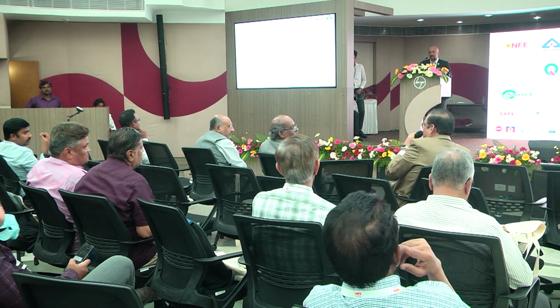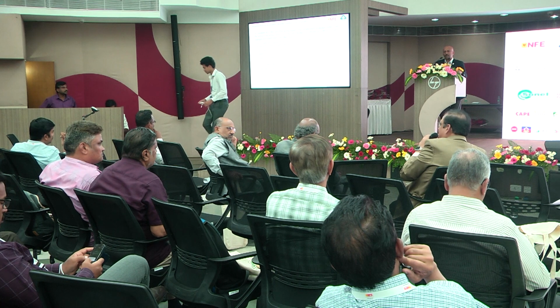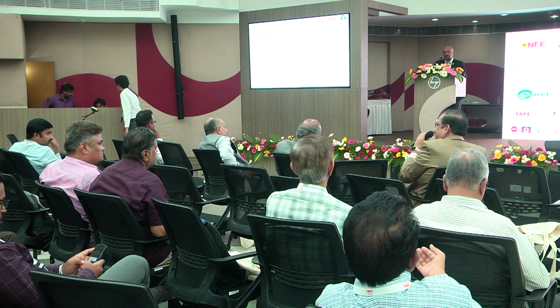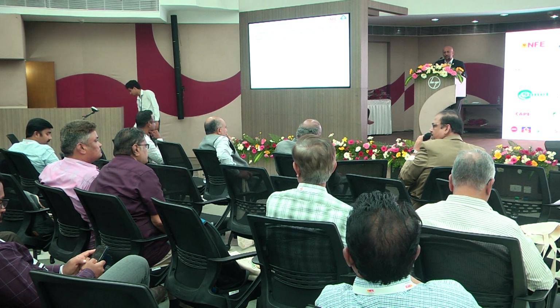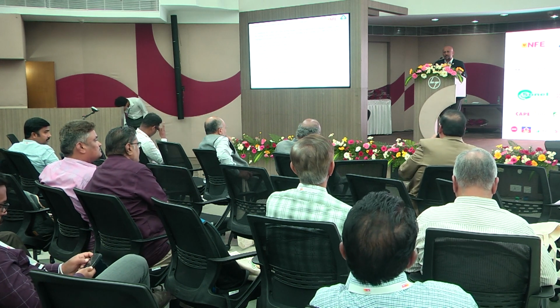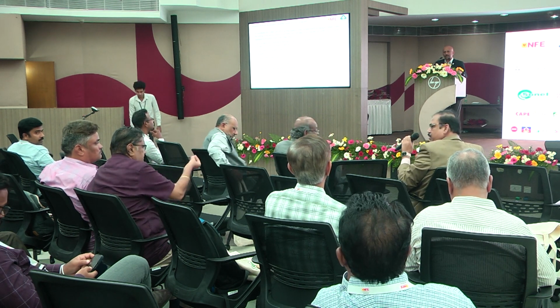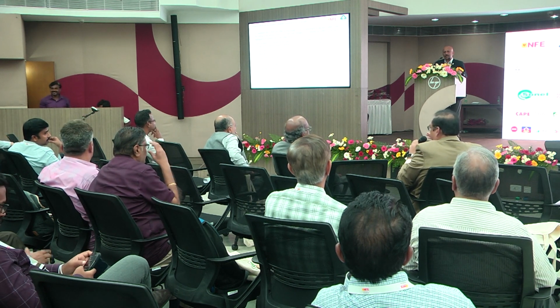See, it's available in the NBC right now. You'll have to have that gas suppression for main panels and critical panels like lift and other things. Probably it's not extended to all the areas, but how we have to interpret it is, wherever he's saying fire safety areas, those sorts of panels should have this compulsorily. That's how we should interpret the code. Probably some more clarity will come in the next NBC. They're already insisting on it now in the NBC.